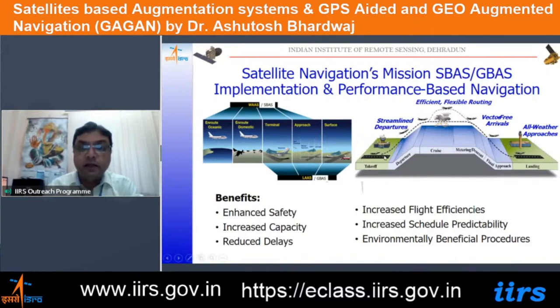So we have a takeoff of the aircraft, and another advantage what we have is that if we are using the GNSS-based systems, we need not be connected with the DME or the VOR systems on the ground, and that enables us to fly point-to-point flight also. Otherwise, we have to be connected with the DMEs or the VORs, and because of that, we have to follow the zigzag path, that you might have noticed. Otherwise, when we are using the GNSS systems, then we can fly point-to-point. So you can see from one airport to the other airport directly in a single line we can travel. In a single line means single line on the earth. That is the footprint of the travel path.